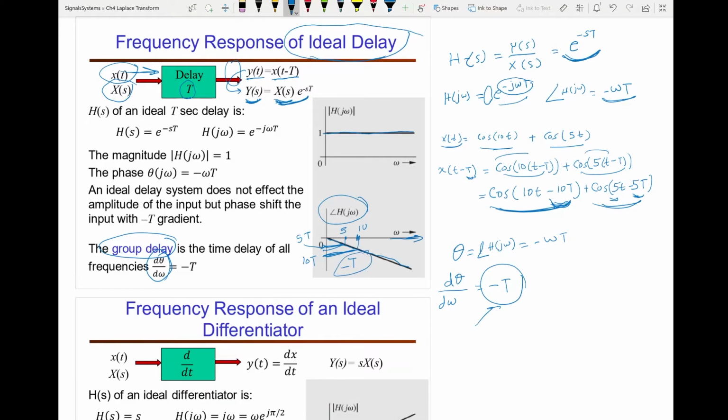In communication, you have an antenna here and another antenna at another location. Electromagnetic waves will be arriving at this antenna from one direction, and the same electromagnetic wave will be arriving from another direction, maybe bouncing from the sky back or traveling directly to the antennas. And each one of them will have different noise. So you're going to have the original signal here and here, but the noise here is different from here. Then we use a time delay to align both signals and add them up.